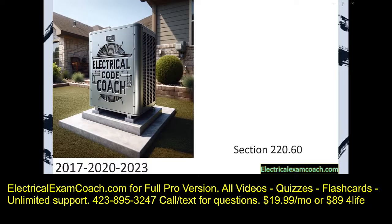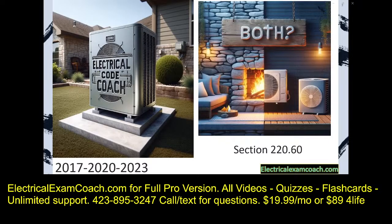The only code that we need to be familiar with is 220.60, and that's talking about non-coincidental loads. Let me explain what I mean. Usually in a typical house, you're not going to be running the heating and the cooling at the same time. So the code has made provisions for our whole house load calc that we only have to count the larger of the two. Let's get to it.